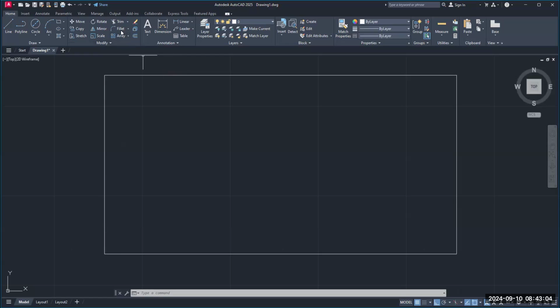So we're going to round these corners by using the fillet command. So select fillet, and it says down here, we need to give a radius for our fillet. So click on radius right here. And we're going to use a radius of 1 inch. Enter. Now watch. Click here, here, enter. Click here, here, enter. Click here, here, enter. Oops.